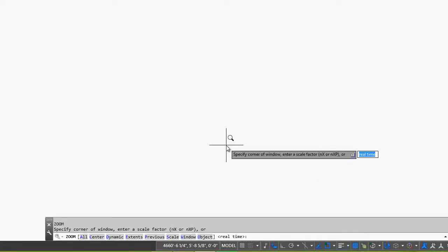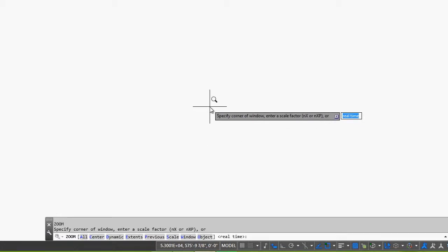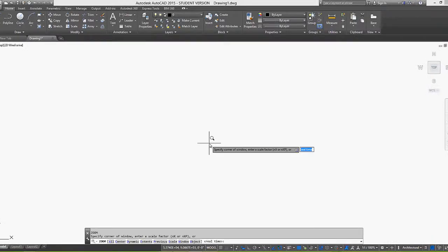or if you're using this dynamic input, you'll notice that at the edge of it, there's a little down arrow, or a graphic that looks like a little down arrow. If I hit my down arrow key, that's going to get me all of these sub options that are the same ones down here. This is exactly why a lot of people prefer to work with the dynamic input as opposed to the command window, and they'll actually close out the command window because you have all of the sub options here as well.